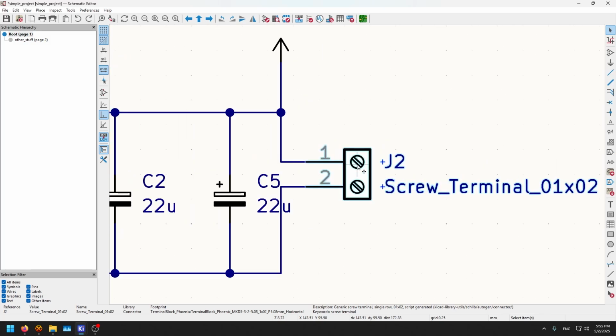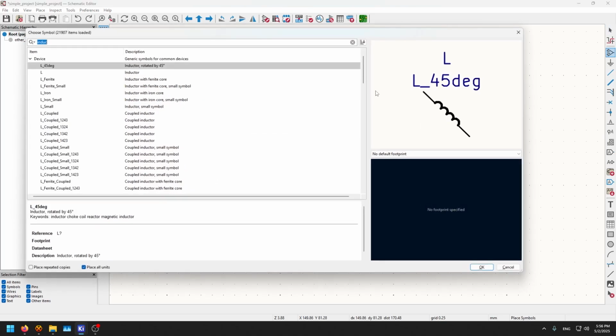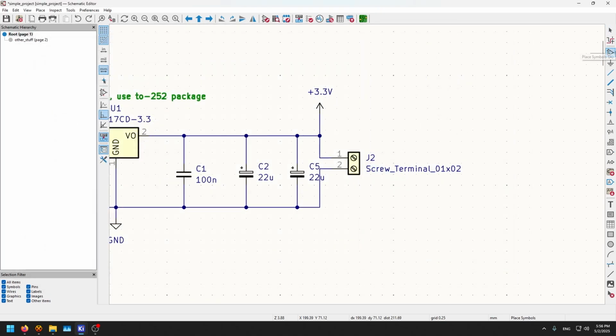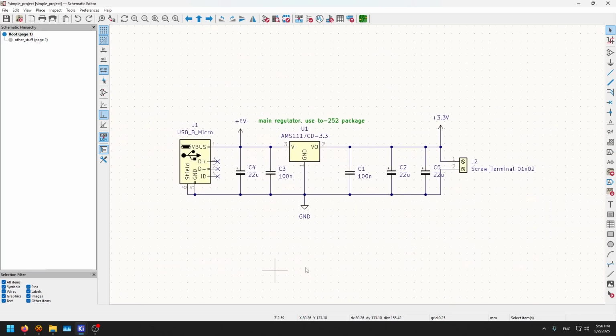If you want something else like this, copy, Control C and Control V. But if you want a faster one, Control D to duplicate. Now it's duplicated, and notice that it takes everything that this one has, the footprint, the 3D, everything, and it uses a J3 directive. What else do we have? A for placing components, basically this tool, and everything else is not really important. I find these tools are the best, and these hotkeys are the most used.